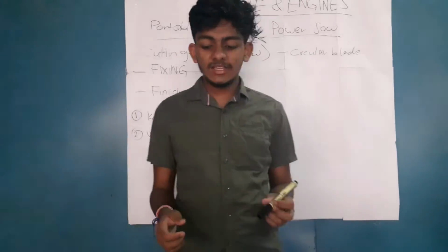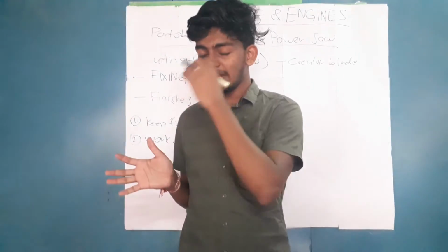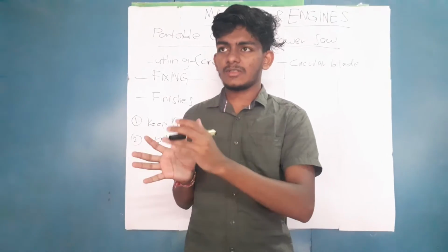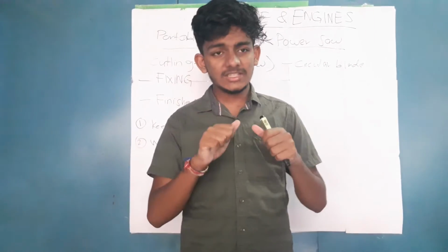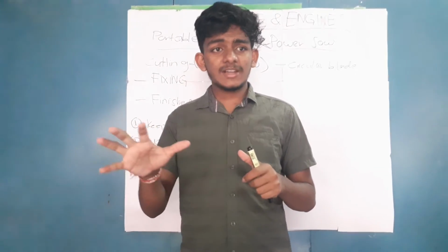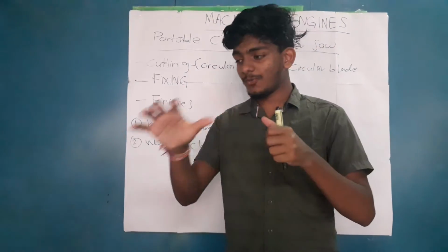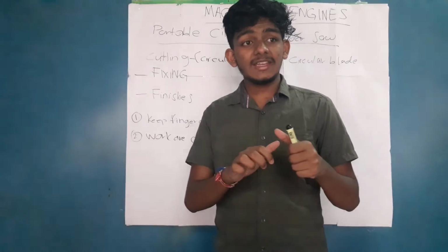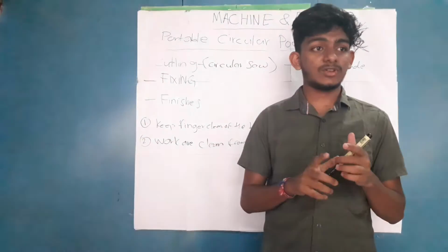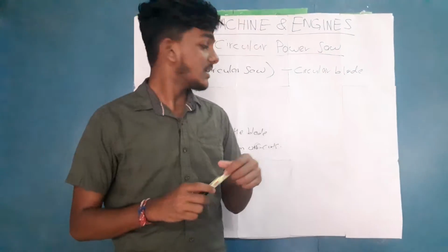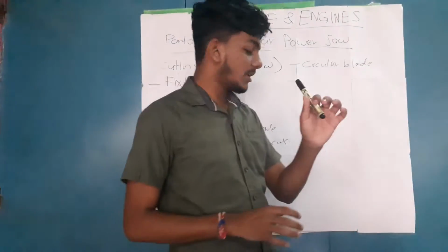Keeping the work area clean means that while working at a required place, you must clear the space around the workpiece. When you are using this circular saw, offcuts will cause a disturbance while cutting, and you will basically use one hand to clear them while you are cutting. In that case, you could end up damaging the pieces of wood that you are cutting. So the main thing is, clear the workpiece before cutting it.